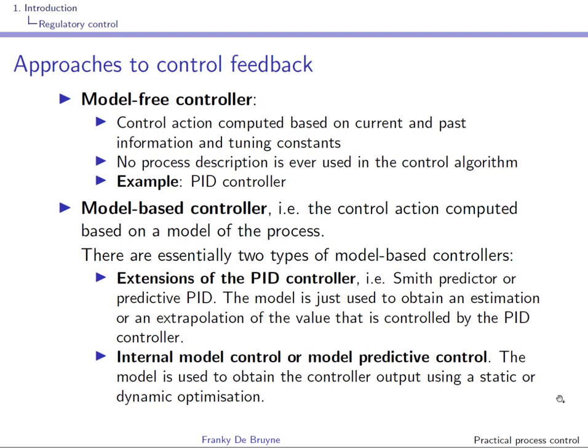The second approach is a model-based approach, but the PID controller is still used. So you can see those approaches as extensions of the PID controller, in the sense that the model is just used to obtain a kind of prediction of the PV that is going to be controlled by the PID controller.